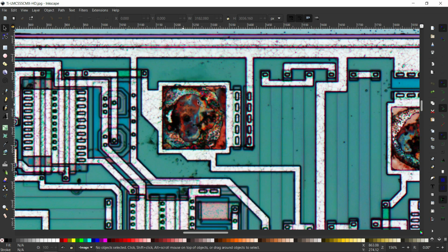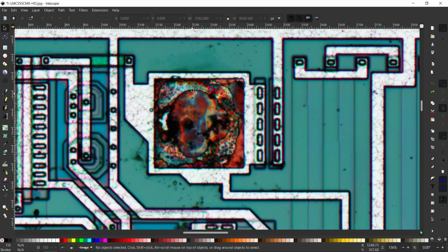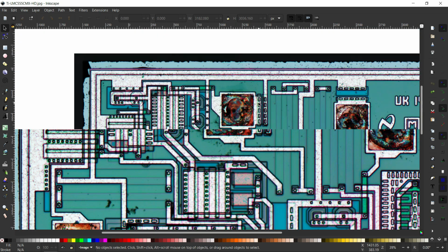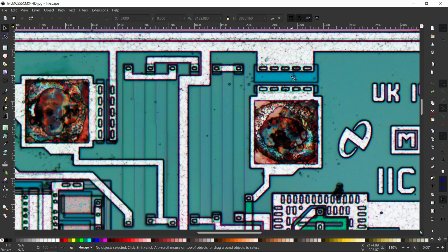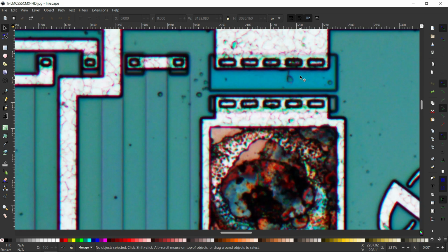So now this is a rough idea about the pad. We have a pad, and next to that pad we have an ESD diode. Wherever you go, any kind of pad, this another pad is also connected here. See here you can clearly see, as we have already discussed in our previous layout, there are something called stretched drain devices. Maybe the source will be stretched or the drain will be stretched. So those kinds of devices are there, stretched drain devices and stretched source devices. In order to prevent the ESD event, they have used a stretched drain device. See, this device is called an LD MOSFET. Maybe they will call this device an LD MOSFET.